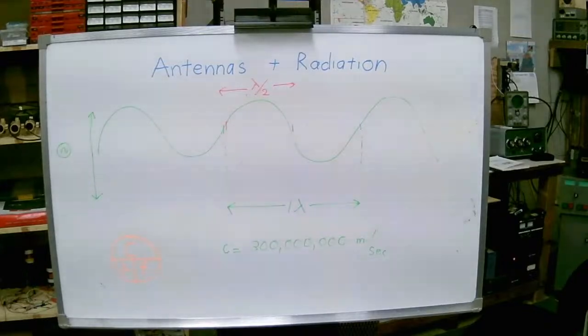Well, what circuit? What example are you specifically? As we're building a, what should we call it, the transistor circuit. Yeah, well, we use coupling capacitors on the input and output because that allows us to pass the signal without upsetting the DC voltages.